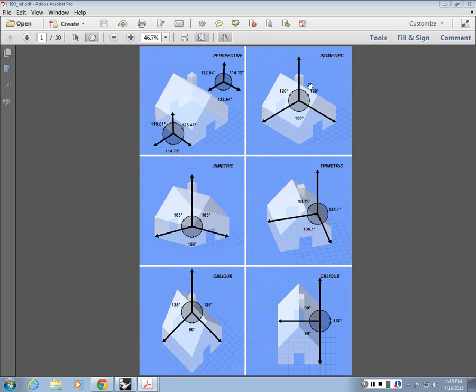Yeah? Would you draw something in the oblique manner, like that would be three-dimensional, so you can see any of those elements inside, you could remove some of the top elements so that you can see inside? Absolutely, that's a good point. So you will draw obliques, like cut out obliques most of the time, to show more plan wall configuration, but the emphasis will be more on the plan because you're seeing more of the plan than the wall facades, right? So wall surfaces. So the view angle is tilted or oriented towards the information you want to talk about or show.